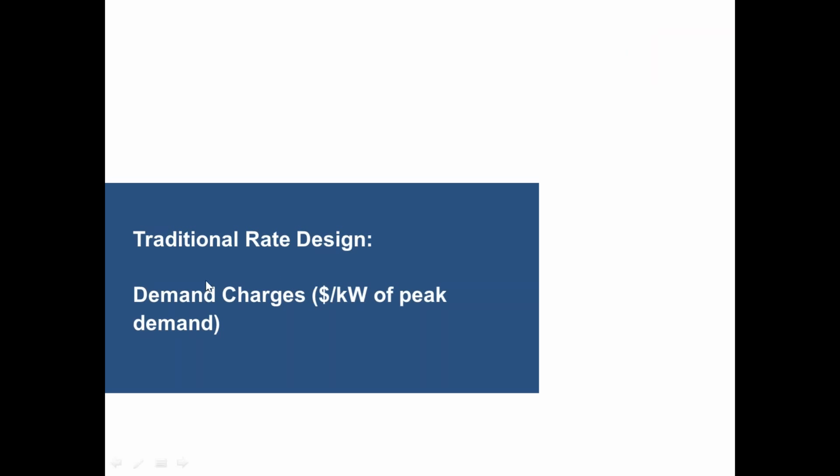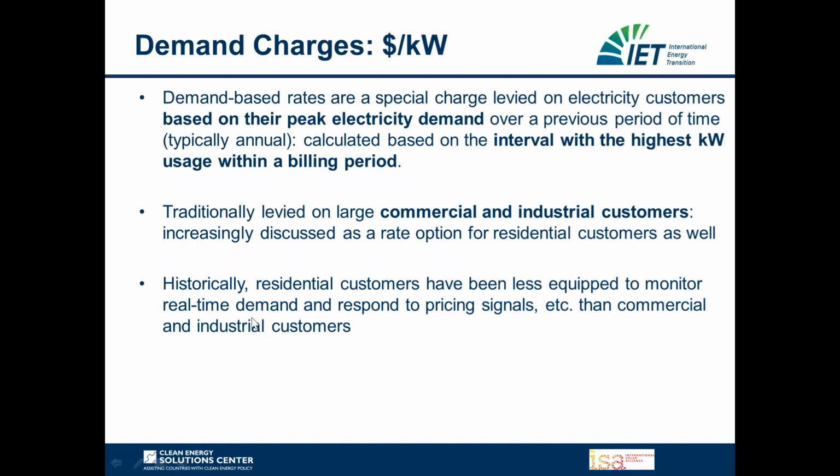So last but not least, when we talk about traditional rate design, we need to talk about demand charges. Demand charges have historically been applied mostly for the larger scale commercial and industrial sector. And as I mentioned before, in previous power systems, which were based on fossil fuels and on large scale power generation units, as a system designer, you always want to decrease or cap peak demand to a minimum, because the peaking power plants, usually gas or even diesel power plants, were the most expensive to operate.